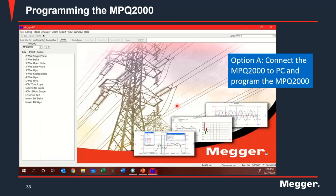Programming the recorder. There are two ways in which you can program the recorder, either directly by actually connecting the recorder to your laptop. So you follow the steps that we covered in the previous slide. You connect your recorder to the laptop, and then to program the recorder, you will either go with Analyzer and Load Setup, or click on Install Setup File, which is the main option that's provided. Both of them are basically the same thing.